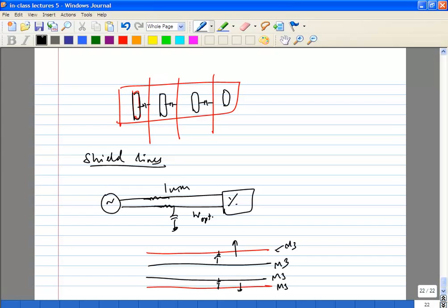You can actually make a multi-layer shield also. For example, if this is on M3, you can add a shield on top on M2 and M4, and a shield on the bottom on M2 also, so you basically make it a square. But remember, this distance you can actually control. The vertical distance between the metals you cannot control. So typically you don't prefer to add a shield on the bottom. If you are going to add one, you typically add it on the sides.